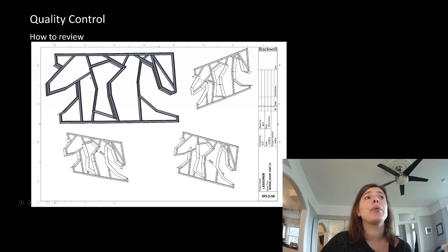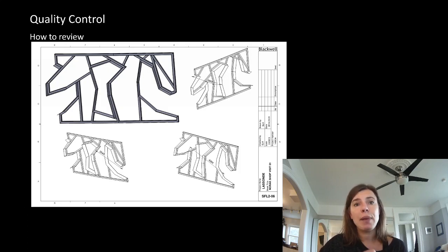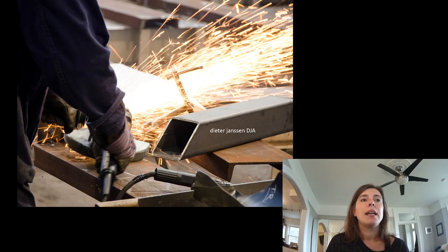So I actually produced, so this was a whole separate contract after that, where they actually hired me to do quality control, where for each panel, we did 2 checks per panel, so 3 measurements from 2 points, so 6 measurements per panel, to verify that they were fabricated as intended.